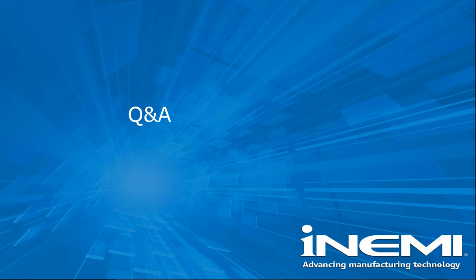Thank you. Any other questions? Hello, I have a question. Yes, is it Jeffrey? Yes. My question is regarding the existing standard in JEDEC A120. It already defines some method for the organic material applied in the package. The method is by weight gain over the moisture. So I'd like to understand what's the advantage of your new method compared to the existing JEDEC method.